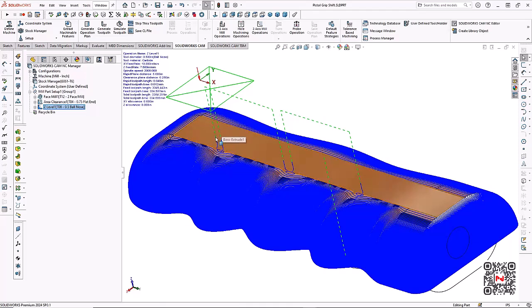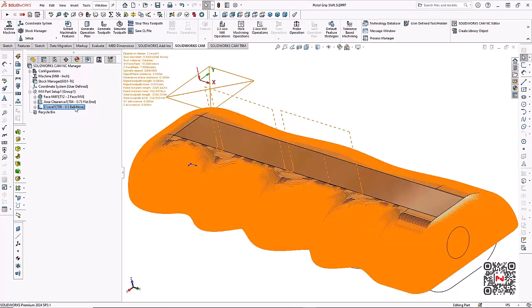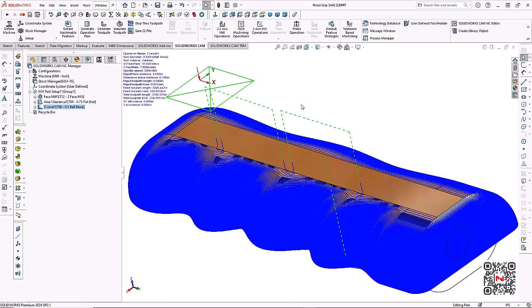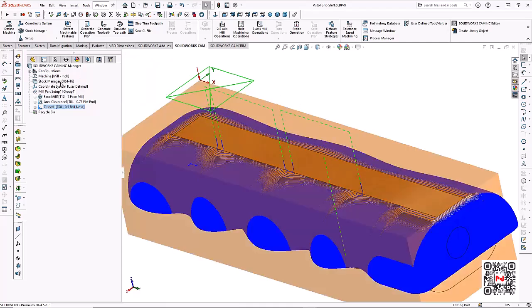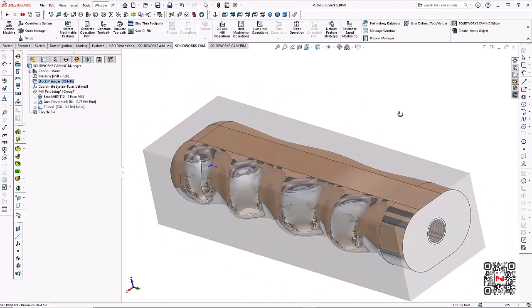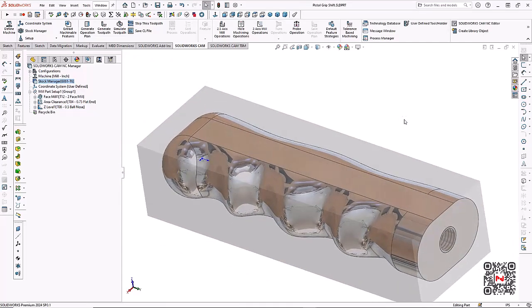And you can see the vertical lead ins and outs also for that toolpath. And again, what I would likely do then is create another setup, flip it over, and use a similar process to create a program for the second side.